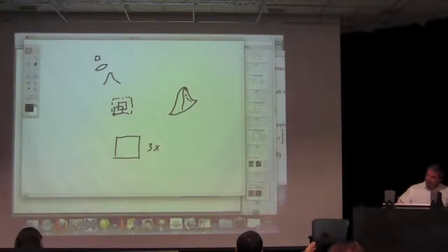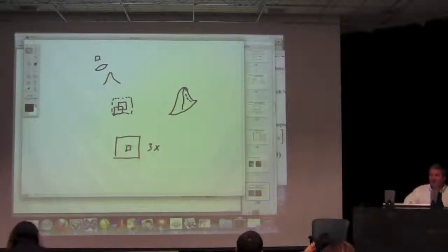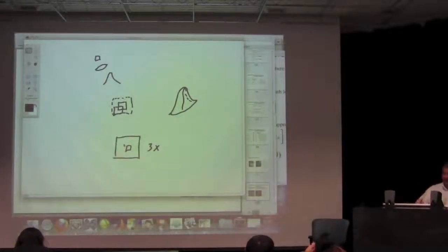Okay? And you should be able to hit the target with a single pure pixel. And that's the one you want to use. You only use one. You want your target to be 3 by 3, but you only want to use the best pixel, the one closest to the center. Right? And that's a terrible idea, because with all those pixels in your sensor, sometimes that might be a bad pixel.